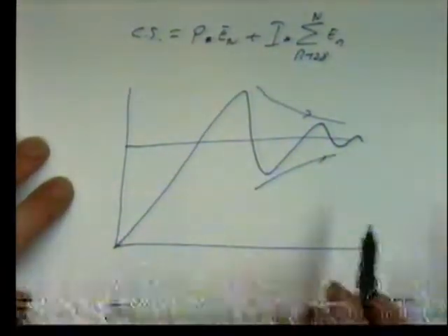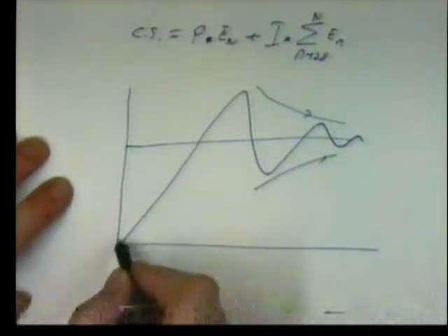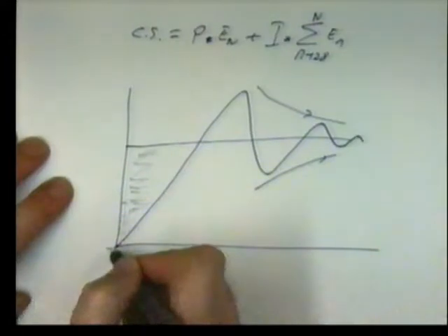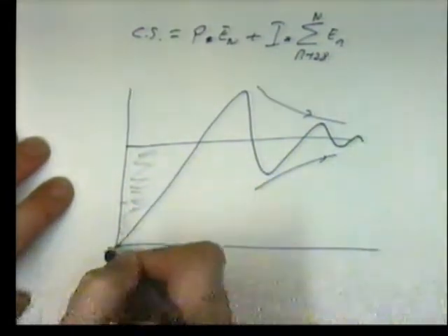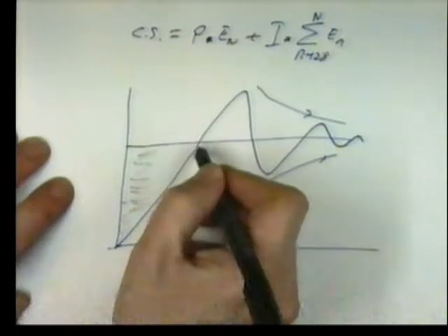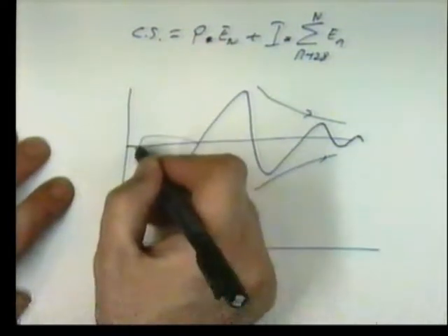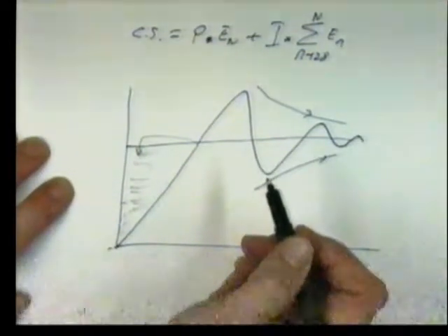The problem with integral control is that if the integrator starts dominating the control system, your system will go out of control. Now, why should that be? Go back to this graph. If we were integrating the error with a pure integrator, we will be integrating all of the errors from the time 0. The proportional term was doing a damn good job here at this point, yet by the time it reaches there, the integral is taking decisions upon information it got from a long time ago.